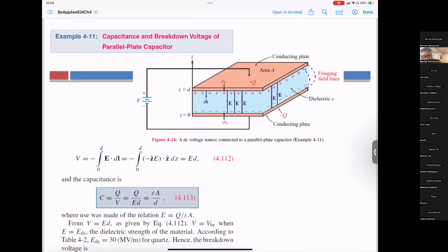geometric situation. Parallel plate capacitors, you actually run into this quite a lot. Fortunately it's a simple situation to calculate, and we run into it a lot, as opposed to some other really complicated scenario of calculating capacitances. The reason is in a printed circuit board, a lot of times you have two metal lines separated by dielectric. And as you'll see, you have something similar in a coax cable.